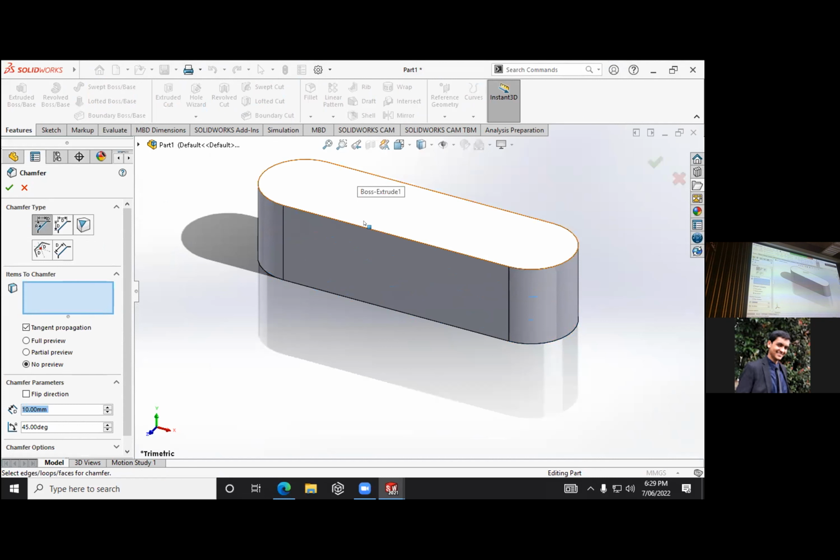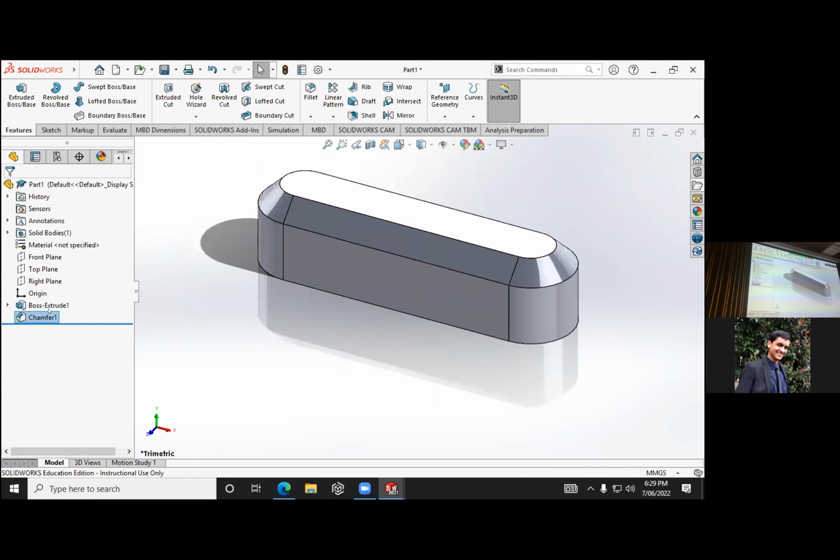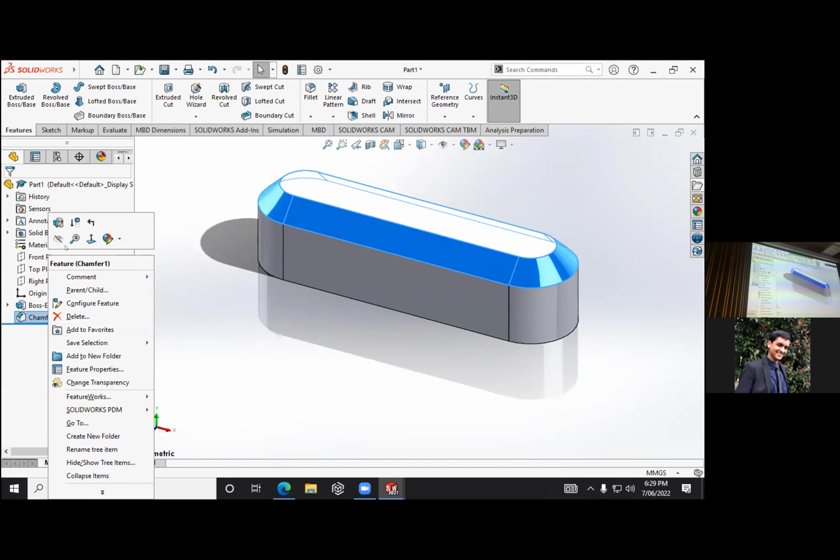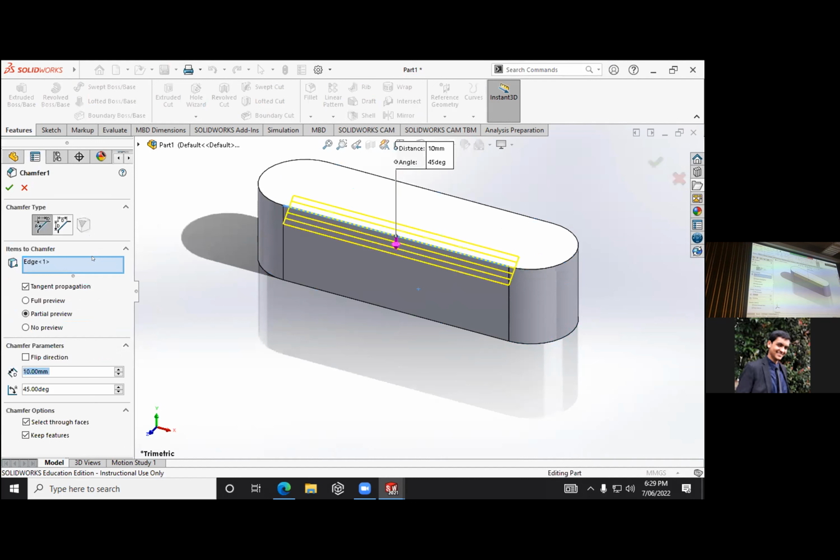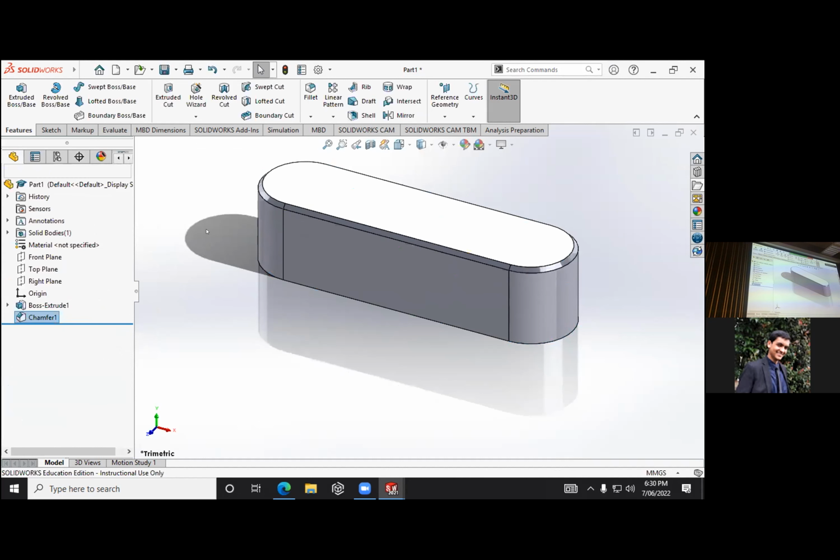Now once you've selected your chamfer operation, you just click on any edge you want to get chamfered. Hey guys, listen up. So now we've selected this edge to chamfer, and if I just click this right now, it's going to fail. Oh, it's not going to fail. So this chamfer is a little too big. So I'm just going to change the chamfer depth to around 2 mils. And just hit OK. And now we have a chamfer on our key. And now we just have that 45-degree slope on that sharp edge. It's no longer sharp.